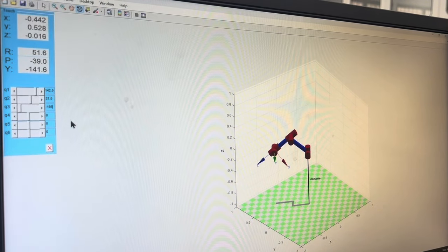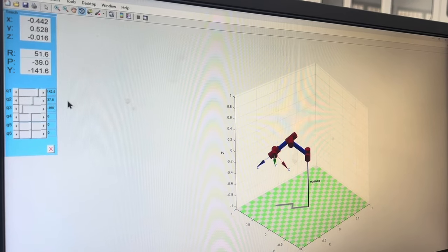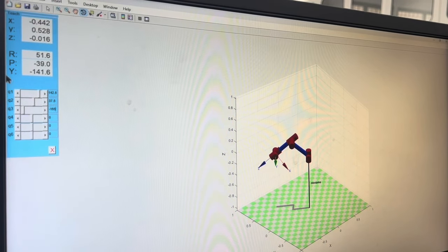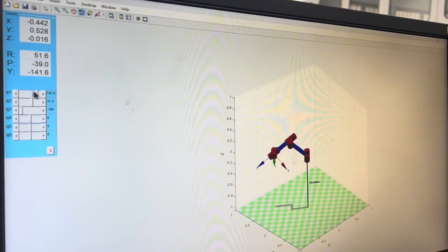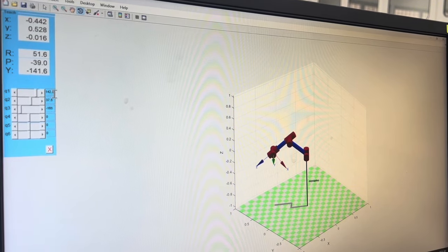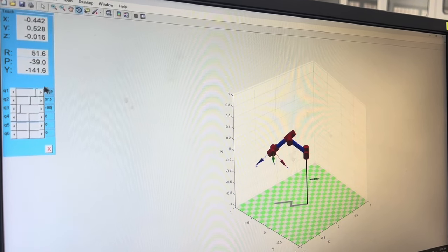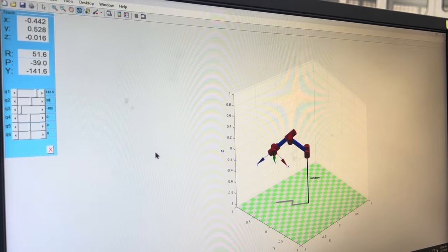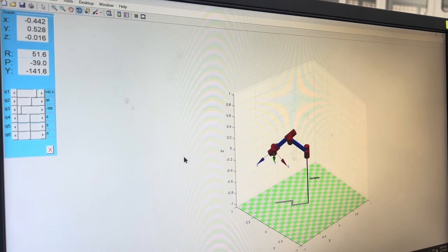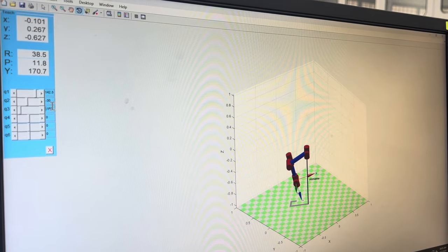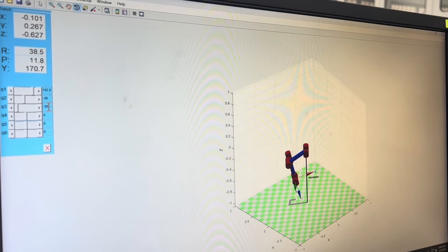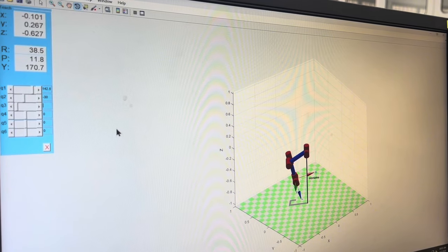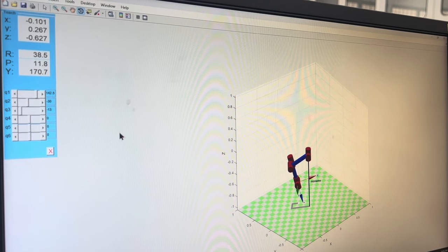So we continue to the place position. Once it reaches the position, the end effector reaches the object accurately at the designated location. So we change the Q2 and Q3 only. So Q2 is 30. Oh sorry, Q2 is negative 30, and for Q3 is negative 135.